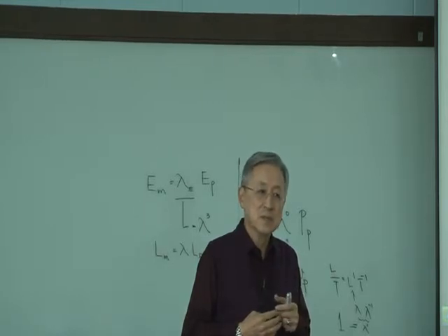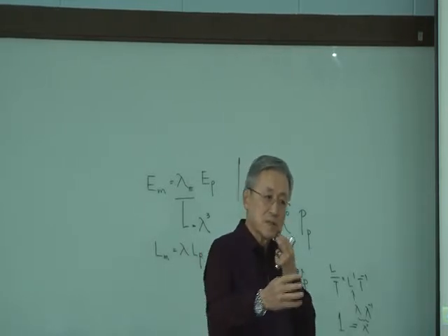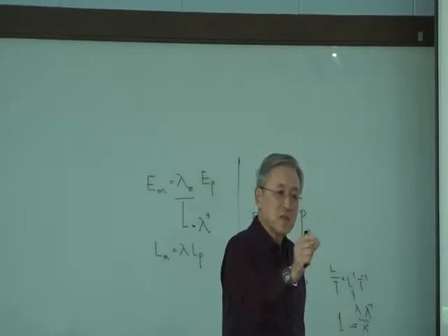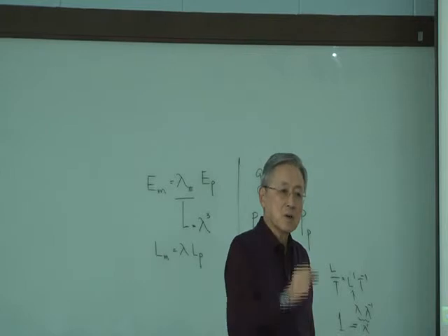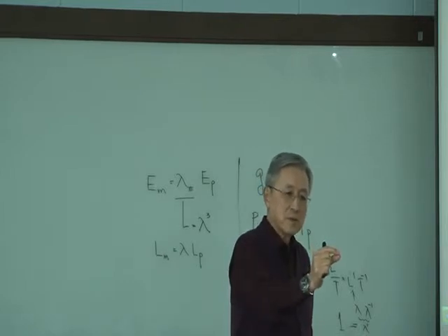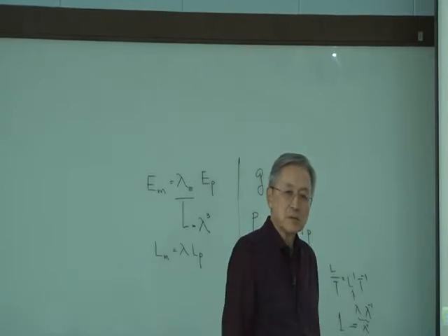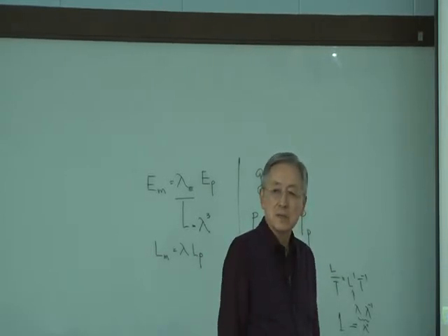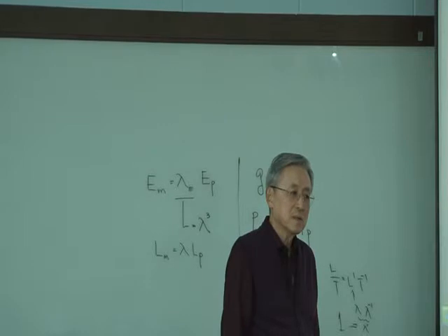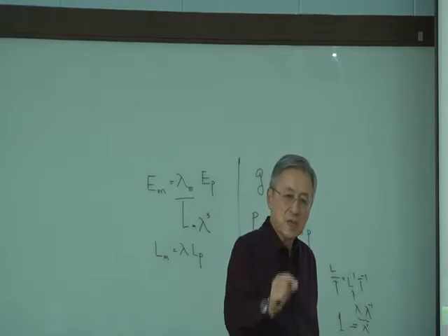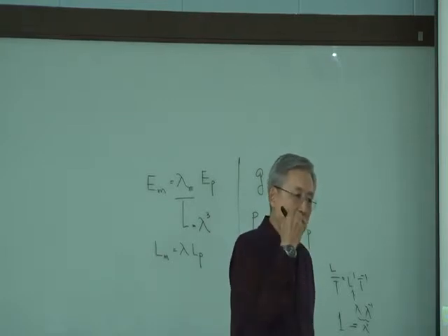Isn't that nice? So in model testing, you usually put the velocity meter or accelerometer. If you measure the accelerometer, you can integrate to get the velocity mathematically, but in reality, it's not really true. The best bet is to get the velocity meter to measure the velocity.